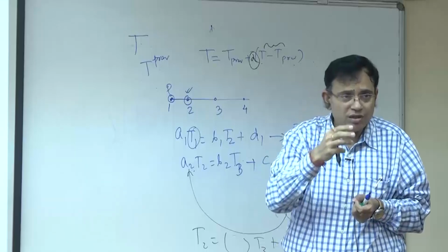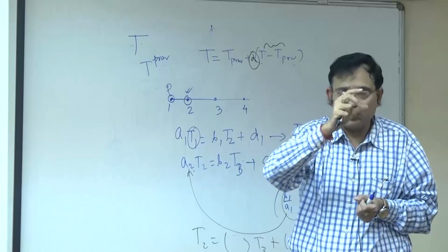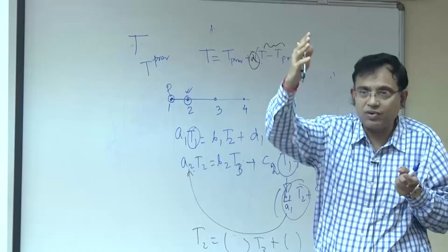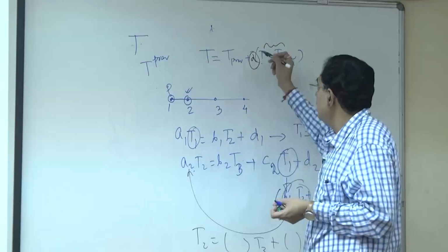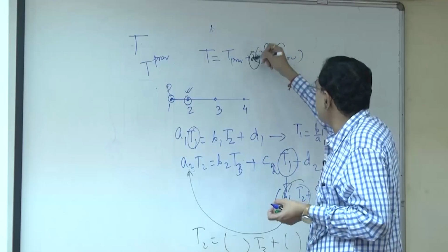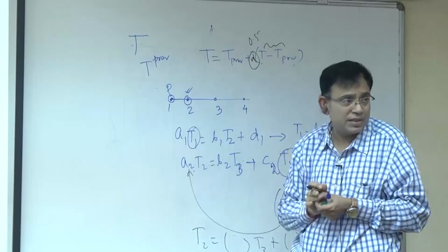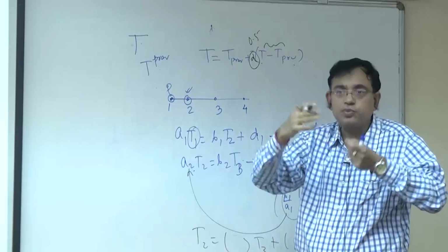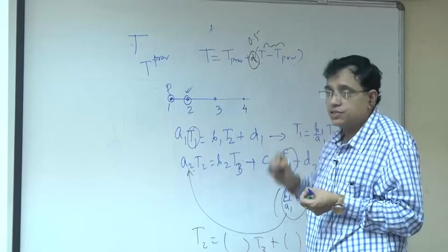So, less than 1, if it is going much out of control, you use a small number, not too small, because then you will never be able to traverse to the convergence, but something reasonable, say maybe it is not that bad, but you want to control it, maybe 0.5 like that, just I am giving an example. But there is no such rule, you have to adjust it problem to problem. So, this is called as a relaxation factor.